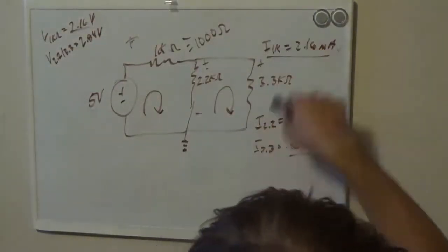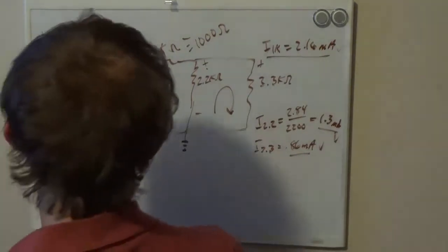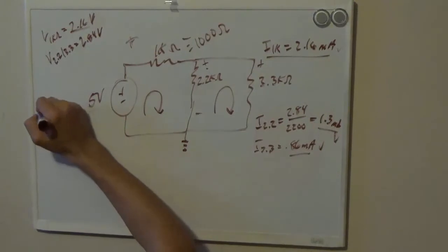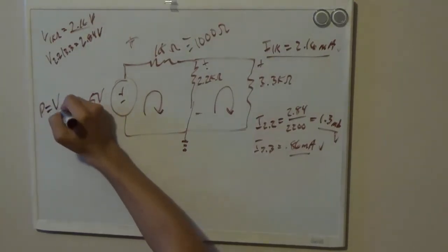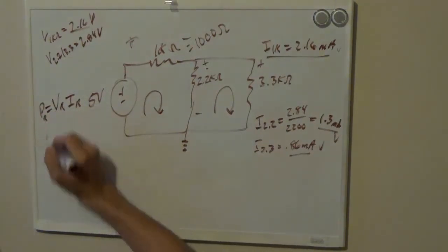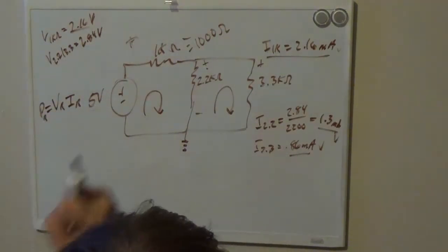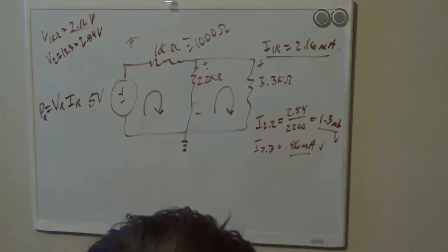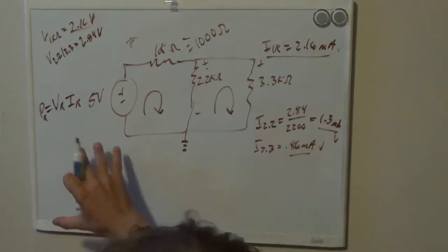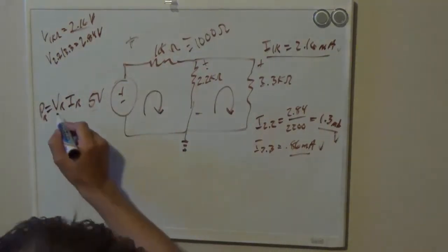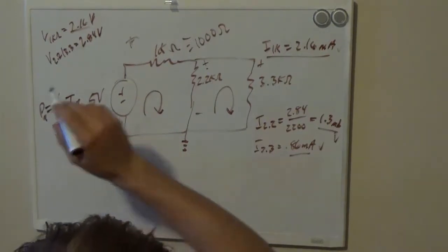The last thing I want to show you guys, since now we know that all makes sense, is we talked about power rating last time. And all I'm going to do is use the first one for calculating the power rating for each one of these. It's the voltage across the resistor times the current going through the resistor. My bad. Voltage is across, current is through. It passes through the element. So that's a day one lesson. Now, it's just a simple multiplication: the voltage of the resistor times the current of the resistor.